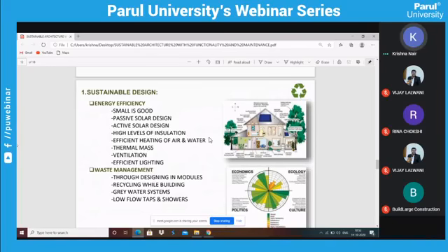Now again, I was talking about these village dwellings. These dwellings were oriented in the north-south direction, and we know that the wind here generally flows from the southwest. So what happens is that the southwest wind is properly channelized. Again, this is a very basic and important part which should be considered while designing a building. So as I said, positioning a building is very important.